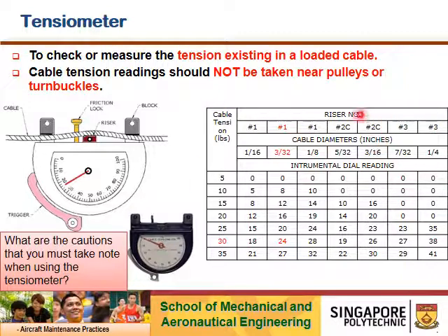The number of the riser represents an adapter used to clamp and create a reading load by hooking onto the cable. Using the previous example, our diameter is 4/32, which is 1/8, so the riser you use is number 1. In the chart example here, they are using 3/32, also number 1.